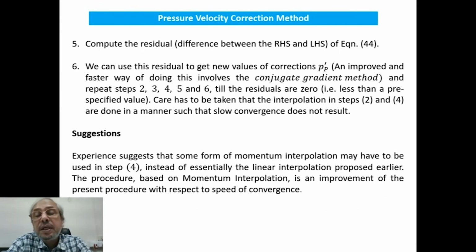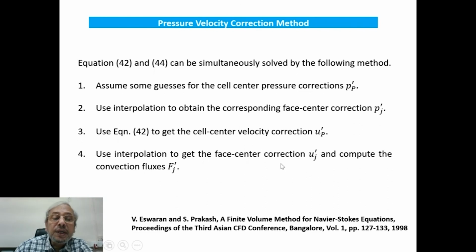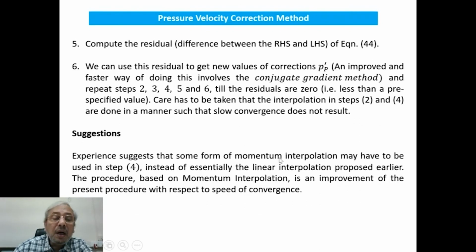Care has to be taken that interpolation in steps 2 and 4 is done in a manner such that slow convergence does not result. Experience suggests that some form of momentum interpolation may have to be used in step 4, instead of the linear interpolation proposed earlier.